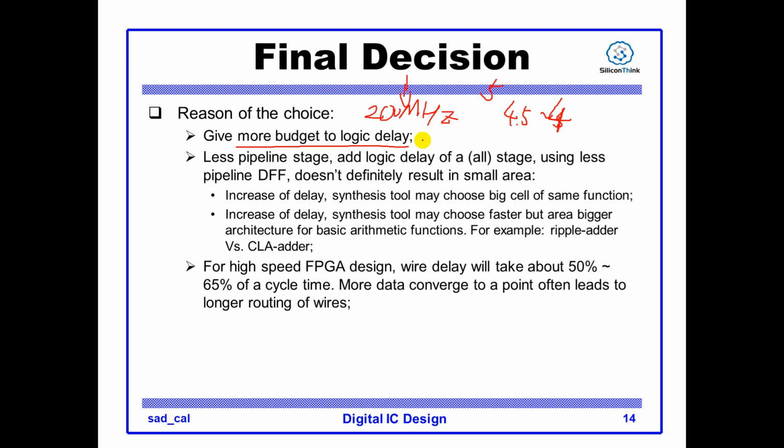This is because in the digital IC or IP design flow, you architect it, then code it, then simulate it. Then you check whether you can run at 200 MHz at the synthesis stage, which is in the later stage of the whole design flow.